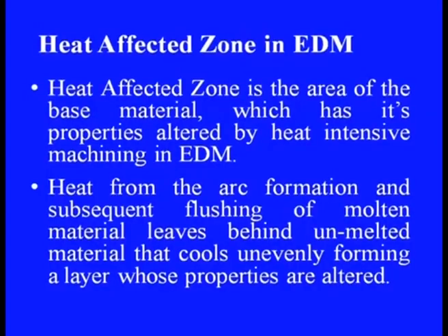Now, let us see another phenomenon that takes place invariably in electric discharge machining. This is called the heat affected zone, in short HAZ. The heat affected zone is the area of the base material which has its properties altered by heat intensive machining during electric discharge.